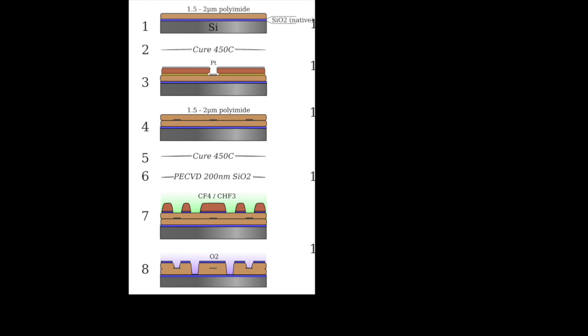Hard masks like silicon dioxide can withstand more aggressive etching conditions and offer better control over the etching process compared to a soft mask. This makes it suitable for processes that require high precision or where a substrate might be exposed to prolonged and repeated etching steps. The next step is to add a copper electrical bus for a future electrical plating step.